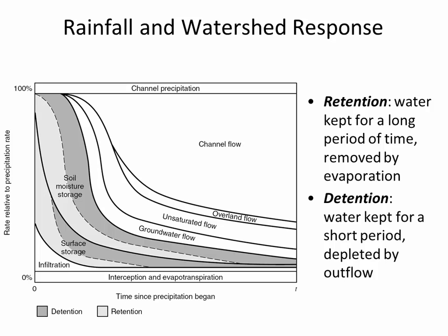That's right. The soil suction or the soil tension decreases as it gets filled up. And so infiltration rate is high at the beginning because the soil is wanting the moisture, but then as it gets more moisture, that driving force that is drawing the water down underground decreases. And so as infiltration goes down, the water has to go somewhere else.